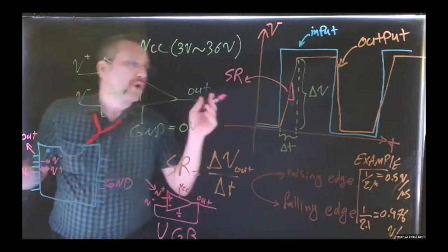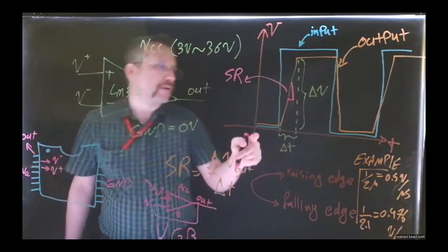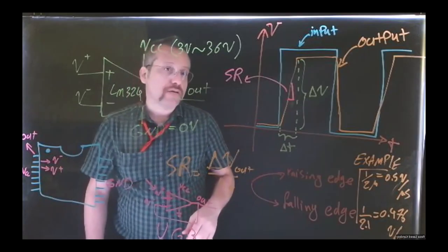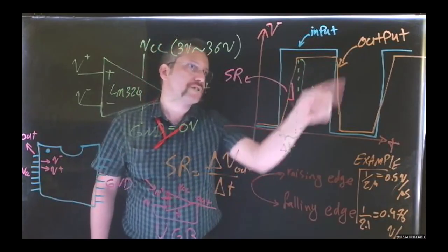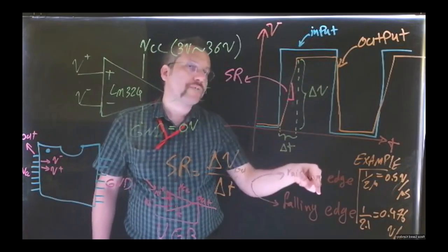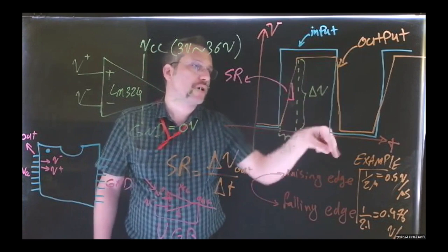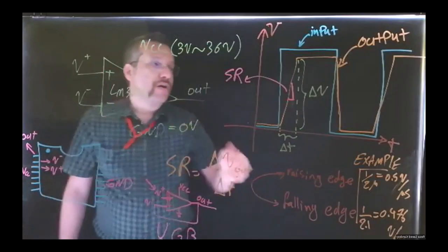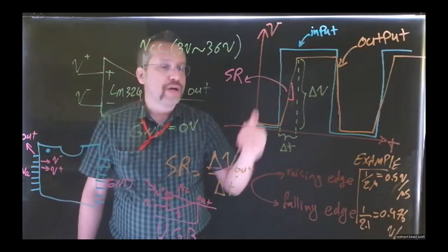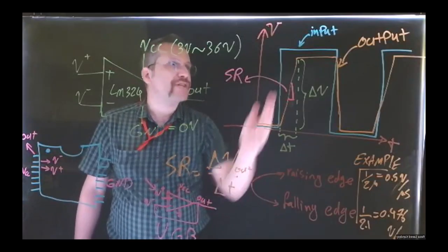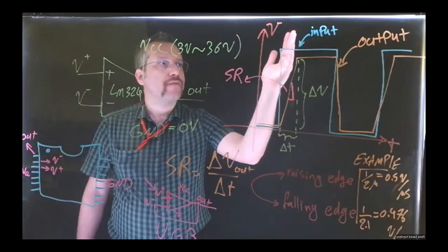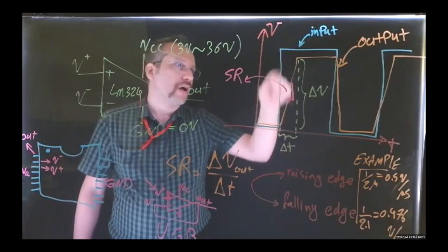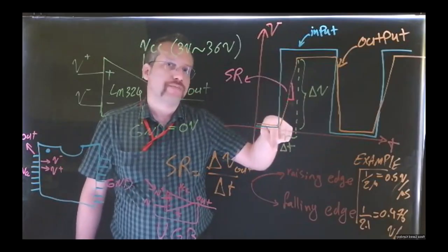Now, what we expect is that if, for example, we have a high speed changing input, like in this example that I drew, a square wave, the blue curve is the input, which is the square wave. The op-amp cannot immediately take the change and apply it to the output. So there is a gradual voltage increase and decrease when it identifies any rapid changes in the input.